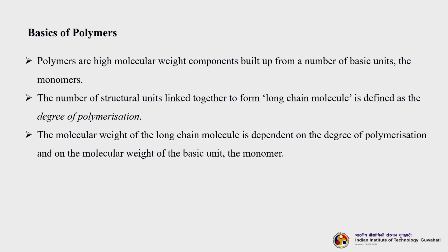So, let us discuss some of the basics of polymers. Polymers are high molecular weight components built up from a number of basic units, the monomers. The number of structural units linked together to form a long chain molecule is defined as the degree of polymerization. The molecular weight of the long chain molecule is dependent on the degree of polymerization and on the molecular weight of the basic unit, that is the monomer.